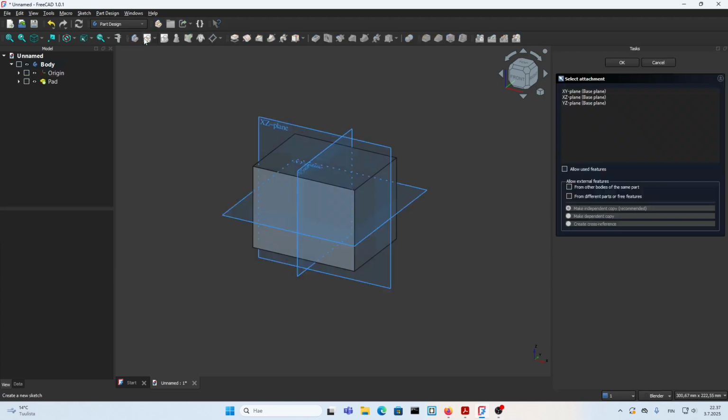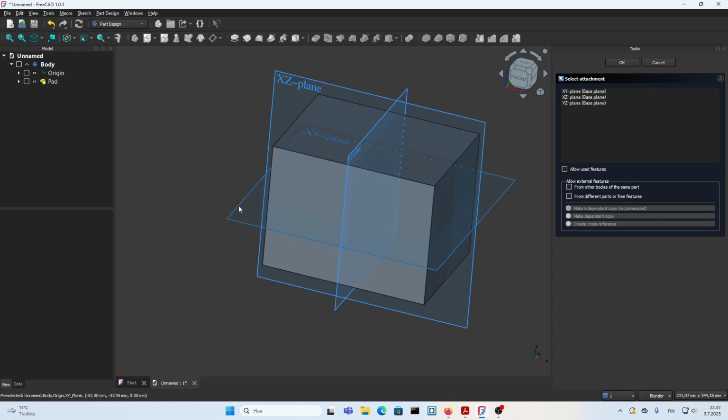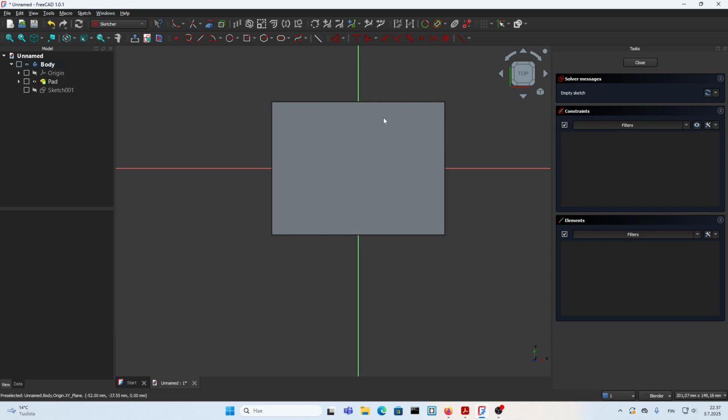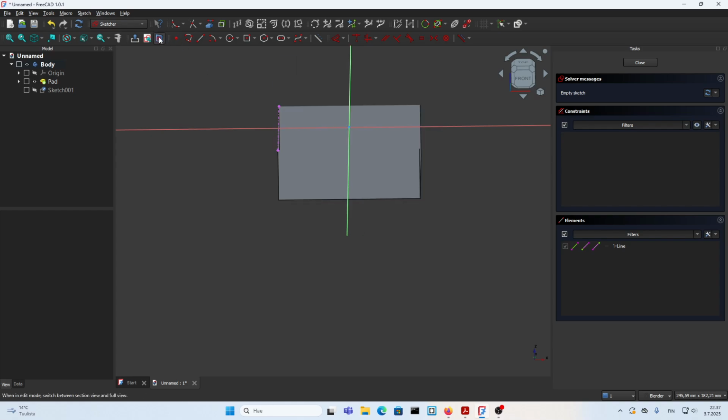Now, after this, let's start by making our circles. So create a sketch, choose the plane. Now I'm not going to make my circle on here. I will choose this plane because I want my sketch to be in the middle of the block. Click XY, external geometry, click on here. If you want to see the section, in here you have view section, which basically shows you the section. I will show it to you from here. If I click again on here, see, this is our section. This is the external geometry, which is now in the middle of the block.